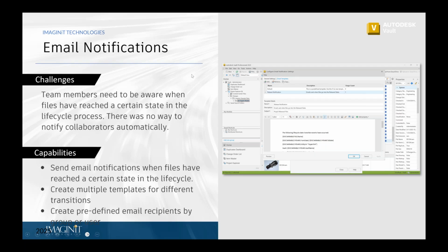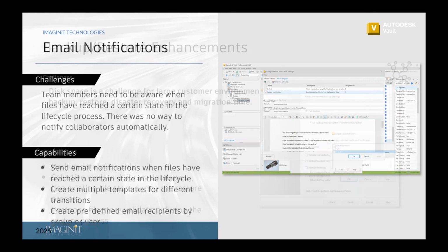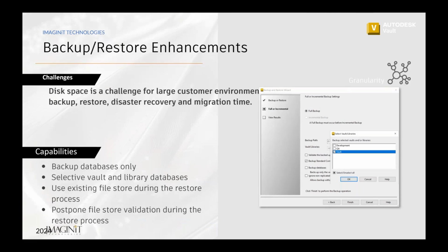A few things with backup and restore. I hit this really hard last year. This was actually part of my Autodesk University talk, how we can back up just the databases, how we can back up specific vaults. That's now been built into the scheduled vault backup, where we have selective backup as well.